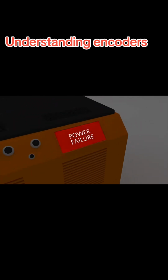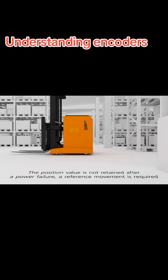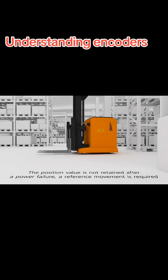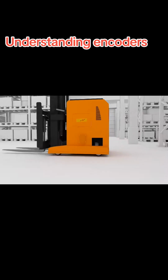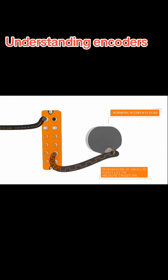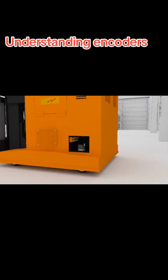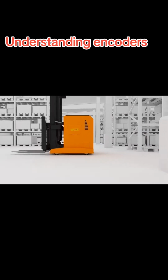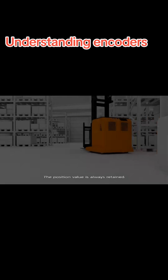With power failure, as we spoke about, your incremental encoder loses the information, so the position value is lost. As you can see here, it doesn't know where it was or how far it was counting. But your absolute encoder will give you all that information because it will continue where it was. There has to be rotation with this one so that it can continue to give you the feedback.